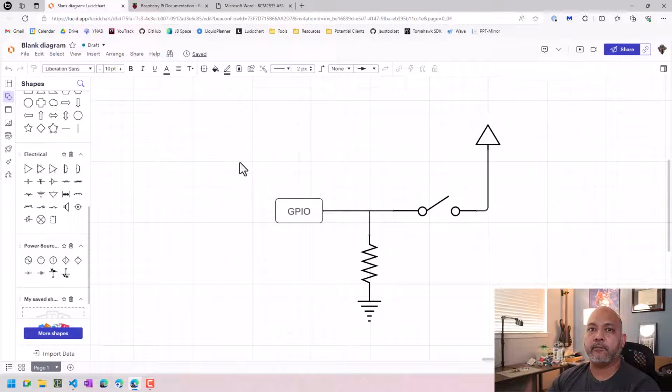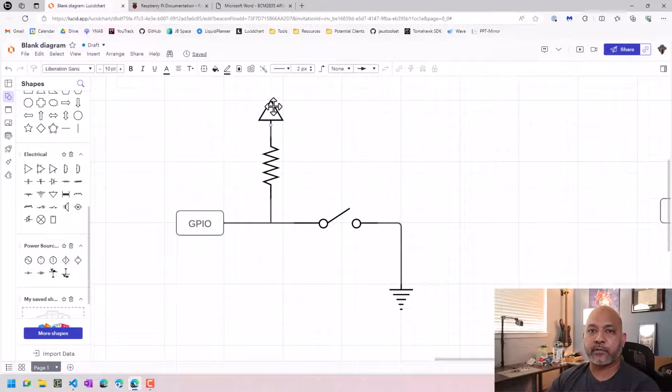Notice that the selection of pull up or pull down resistor impacts the direction of the switch that will indicate a high value or low value. In a pull up resistor, when the switch is open or off, the GPIO pin will read a high voltage. And typically, high voltage is read as true in positive logic.